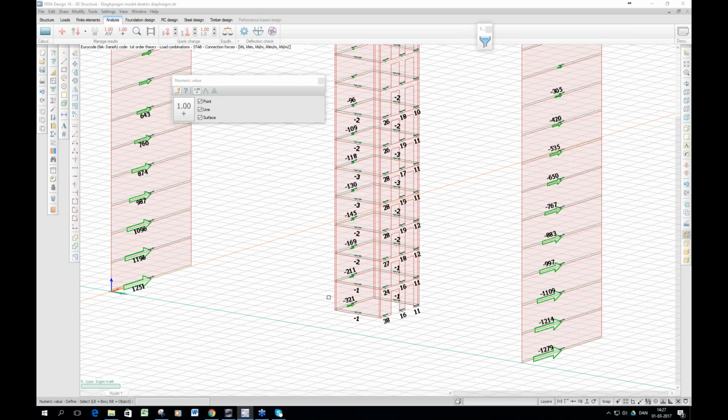Also for your vertical joints between the prefab walls, you can control the forces there, so you get the distribution of the loads exactly as you want. This is a huge thing for us, and will also affect the supports, so that you can put a point support, like a pile, and say this pile can max take 100 kilonewton, whatever, and then everything above 100 kilonewton, distribute to the neighbor piles. So it will be a linear elastic plastic stress-strain relation material model. This is quite a big thing.